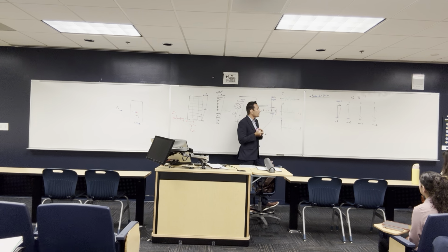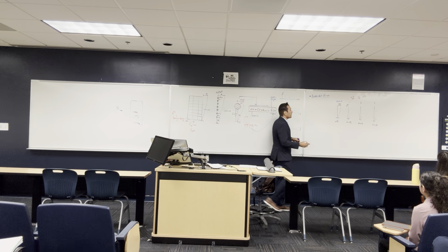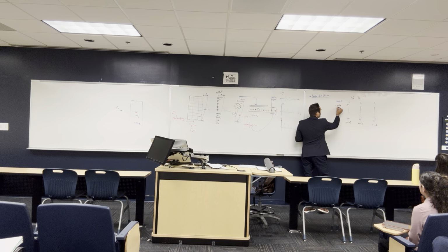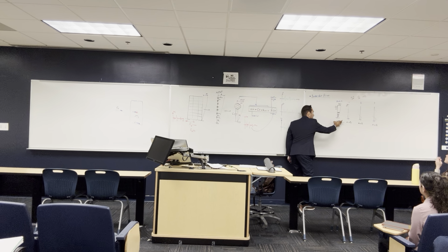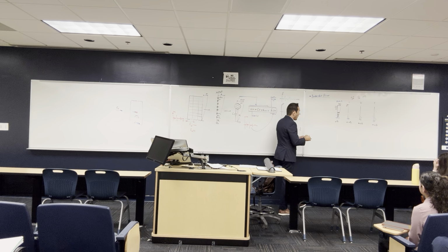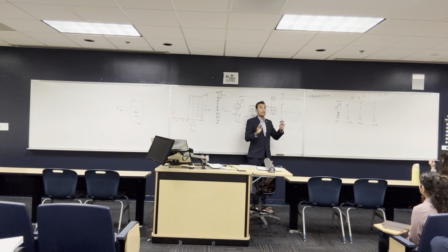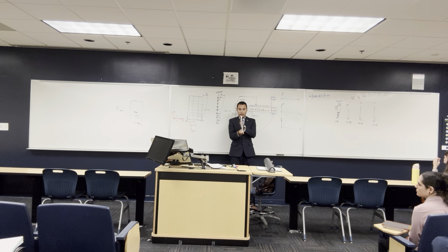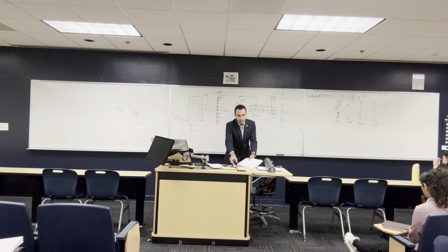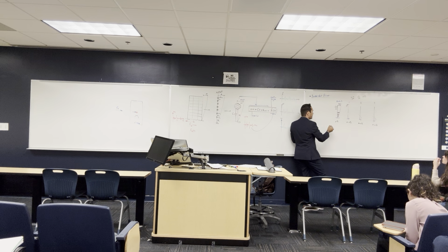Why are we doing this? Because at the end of the day, I want to calculate how much force each story has. And the amount of force depends on the mode shape. This one is going to give me negative force. This one is going to give me positive force. But anyway, let's keep it that way, that this is the mode shape of the building. And each mode shape has a period. Like the time that this building needs to go this way and come back to the original position, that's the T of mode number 1.